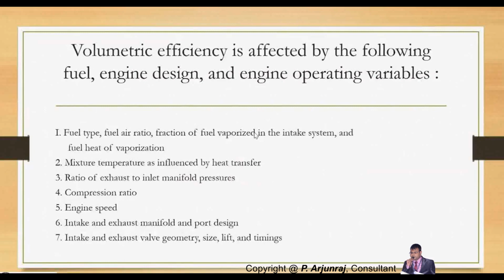See, the volumetric efficiency of the engine is affected by various parameters, based on the engine design and also on the operating variables of the engine. It also depends upon the compression ratio, the engine speed (RPM), and how you design the inlet and exhaust manifold and the port design. You need to design it in such a way that there is a smooth flow of air through the intake system so that you can increase the volumetric efficiency. And the valve lift, basically the geometry, is very important.